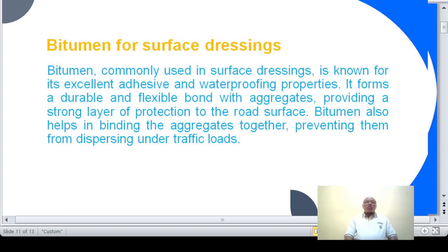The correct choice of bitumen for surface dressing work is critical. The bitumen must fulfill a number of important requirements. They must be capable of being sprayed. They should wet the surface of the road in a continuous film. They should not run off a cambered road or from pools of binder in local depressions.